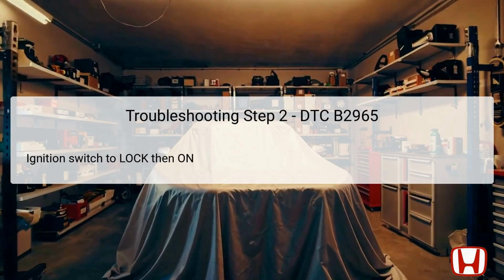After clearing the DTCs, the next step involves turning the ignition switch from the lock off position to the on position. This process is essential to reinitialize the vehicle's electronic systems, including the HVAC control modules.